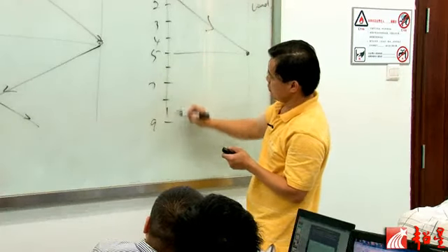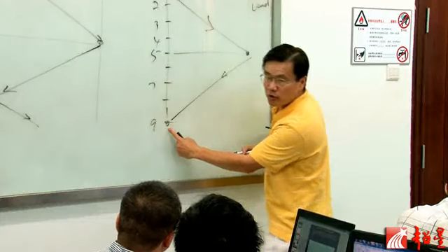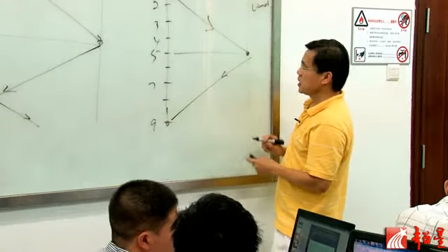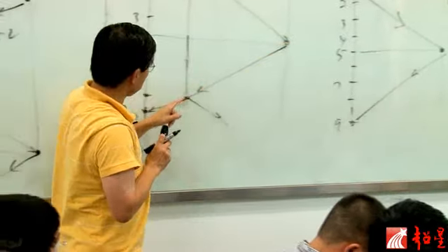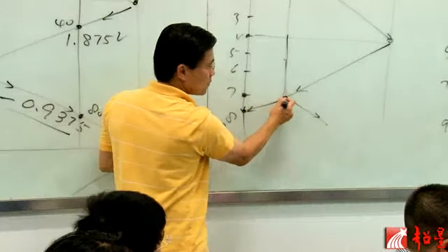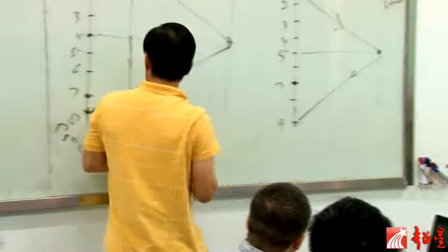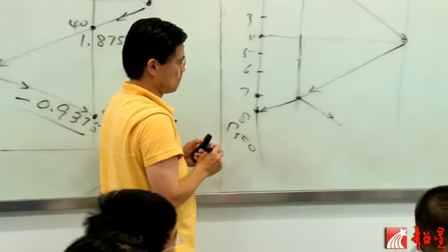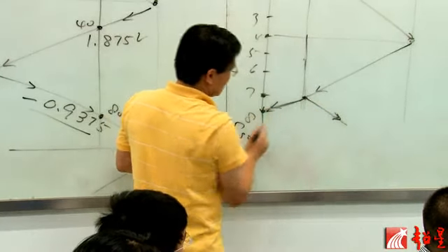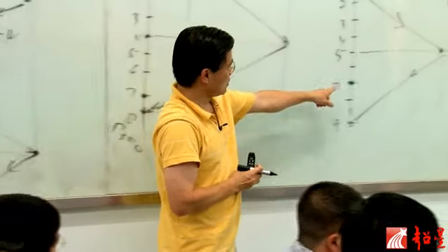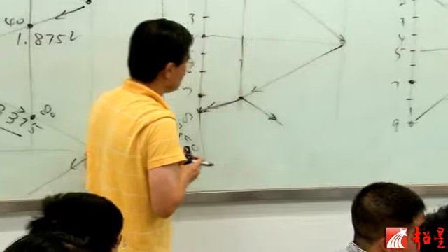It takes 4 nanoseconds to reach the middle point. Remember, this is the middle point. In the meanwhile, this voltage here is going to reach the middle point at 7 nanoseconds. Right? So at 7 nanoseconds, what's going to happen? There's a reflection here, there's the incoming voltage here. There's a voltage that's launched at this point. What is that voltage? Where is it?